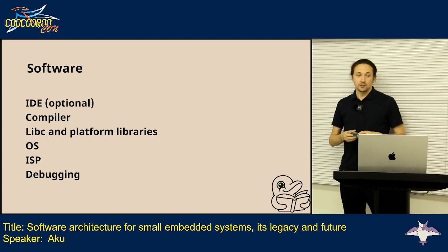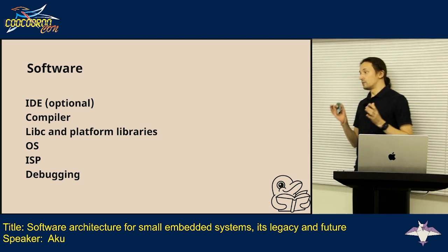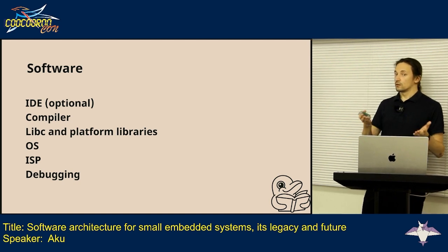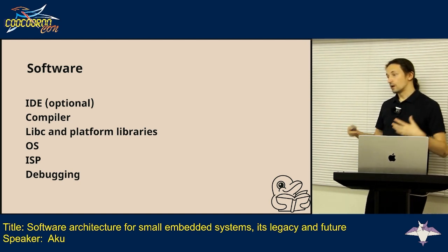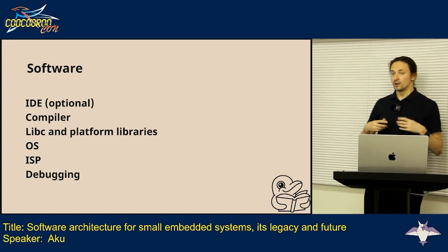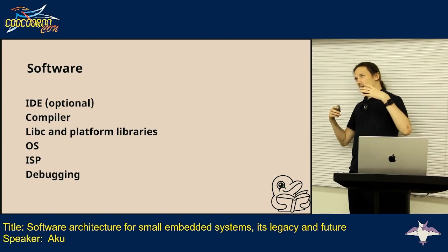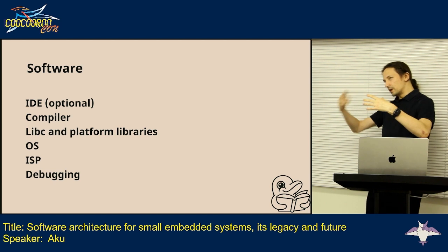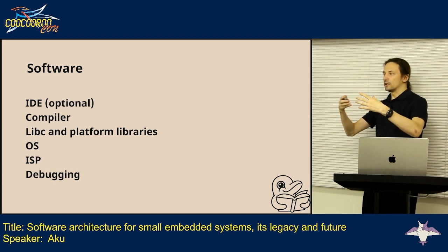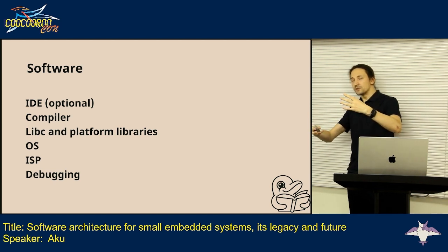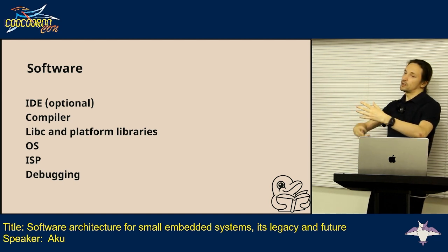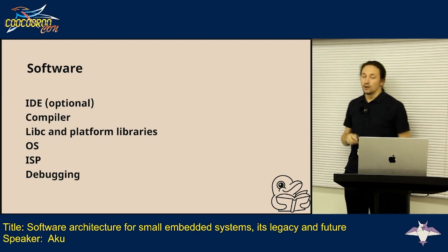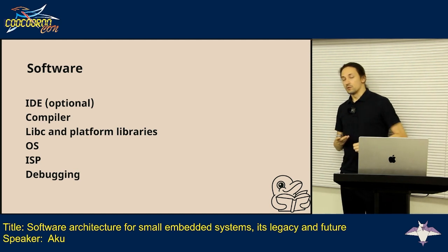In some cases, you may also want to do power profiling, and a lot of modern tools from ST Microelectronics and Nordic also integrate this feature. So at the same time you can debug your chip, see what exactly happens, like trace interrupts, trace function calls, and at the same time see the power consumption of the whole system or specific blocks.